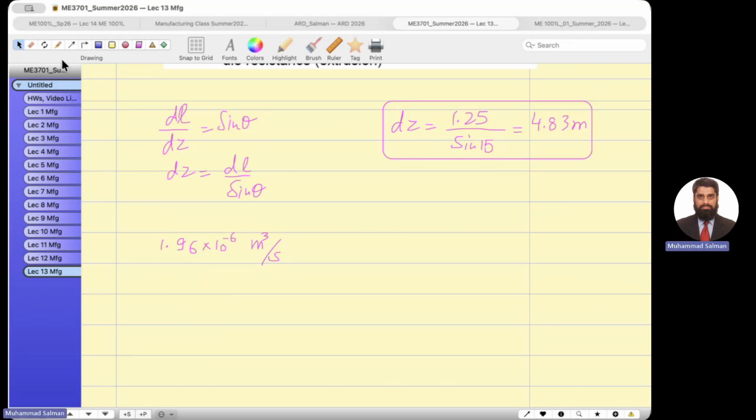So because Q product equals the Q screw, it has a formula: W times velocity along the helix lines, Vz, times h, the height of the channel, minus W times the height of the channel cubed divided by 12 times eta, and dp over dz. So let's plug everything in over here.